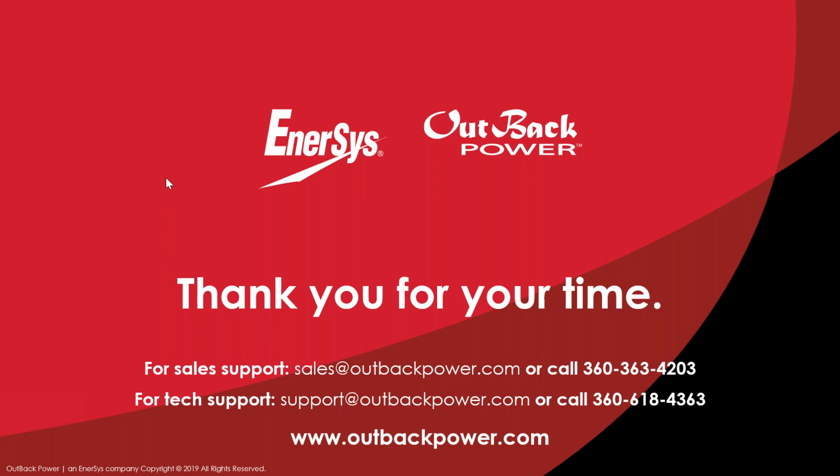Oh, interesting. So you expect the industry on the battery side is going to move to cycle counts versus years? Yeah, I really think that's the way it's heading. Especially with lithium batteries, that's how most manufacturers are doing it. I expect lead acid will probably move that direction also. It's hard to say, because years are hard to gauge when other things affect it, like temperature. So I don't know if we'll move that way with AGMs, but for sure lithium is heading that way.